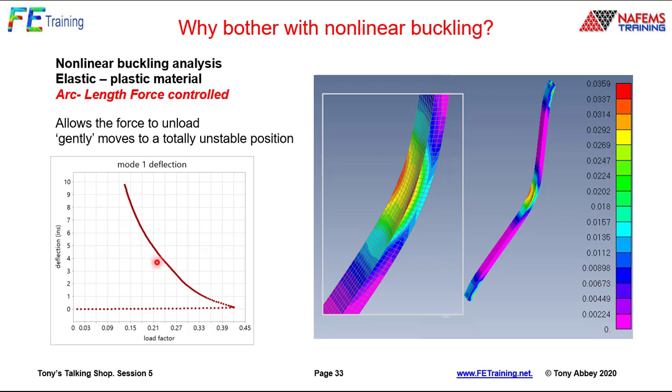So we're taking the load off. It's softening very, very clearly, and it does actually allow us to see more of the kind of shape that it would develop as that plastic hinge is developing further, but again it's just softening off. So it's running away, let's take the load off quick to see if we can explore a little bit more what's going on.